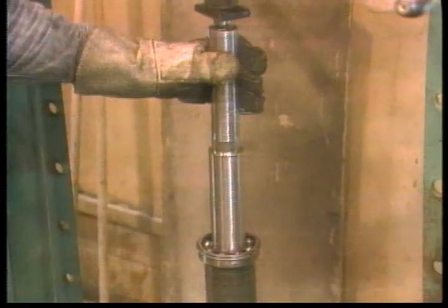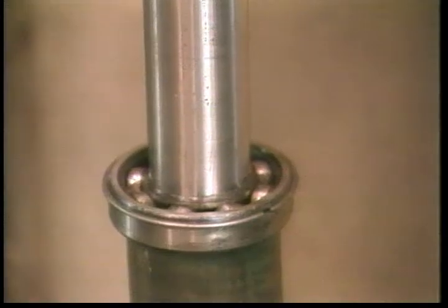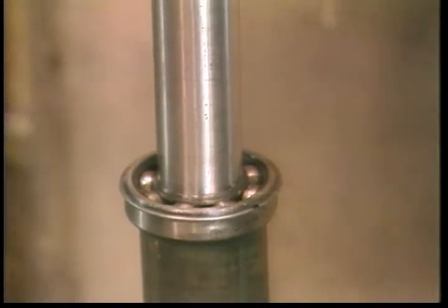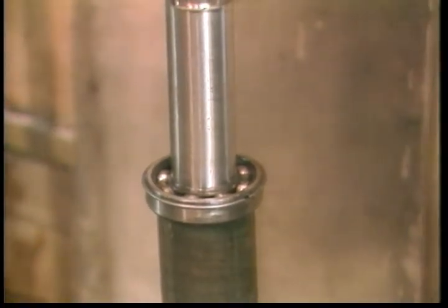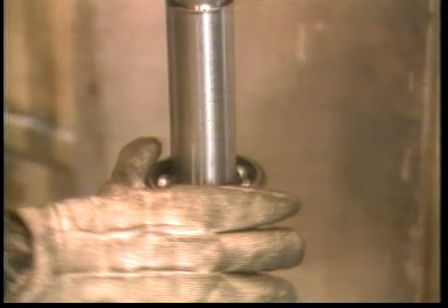Since a bearing will sometimes move as it cools, make certain it's kept in place until the temperatures have equalized completely. Sometimes a shrink fit will expand the inner ring, reducing normal operating clearances and causing the bearing to bind. Make sure the bearing rotates smoothly after it is cooled.